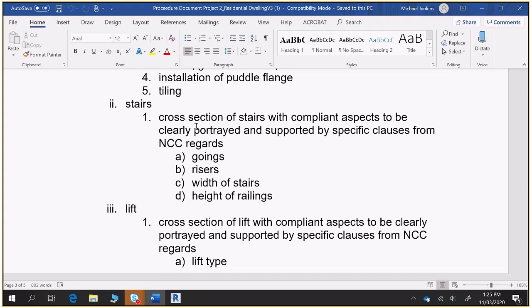Spot on. So that's the cheap way of doing it, and you see that done around the place with bathroom renovations. People just build up their floors, and at the bathroom there's a step up. But it's not a nice detail. The best way to go about it is if you actually chip away that floor and you set that floor down, and then you do.